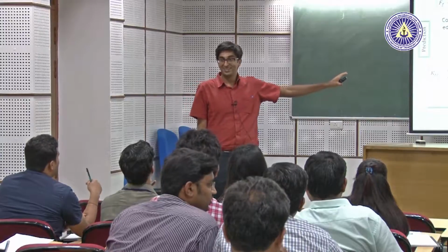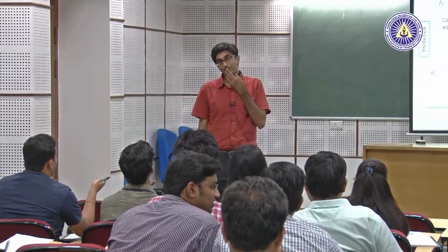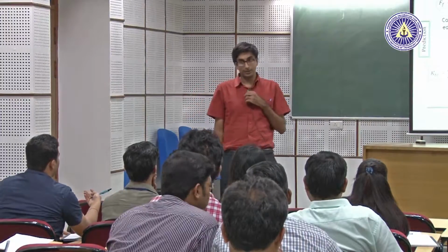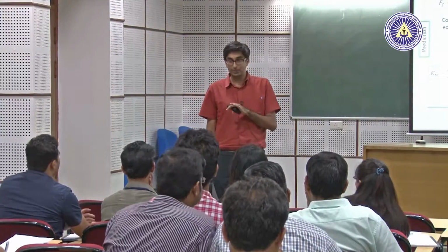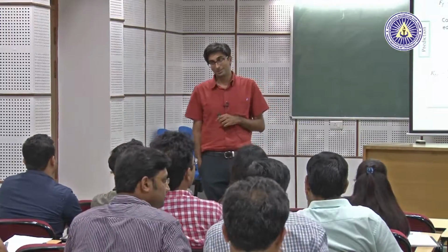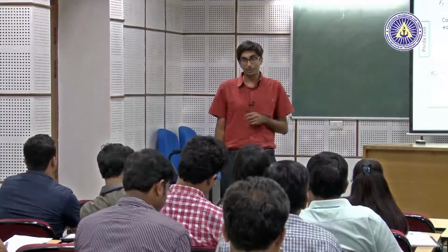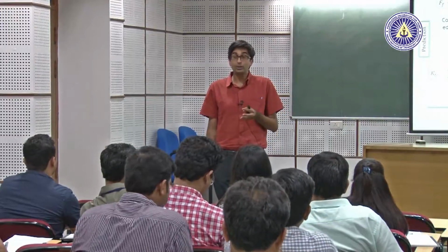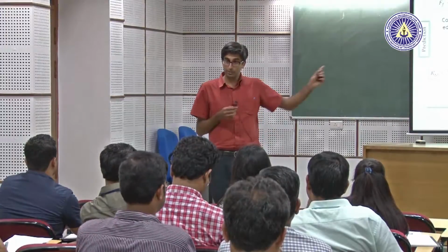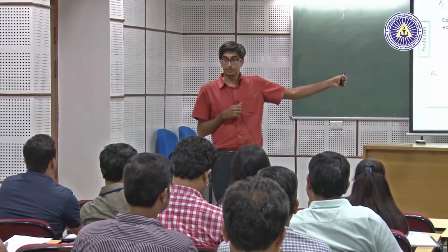Let's say there is an ISO insert, so I can use it for external turning as well as internal boring. If it's the same insert, same tool, same material, then it's okay. Then it should not change. You can measure and see. It should not change so much, because what has changed? Tool is the same, material is the same. Nothing is different because this is only a function of those properties.